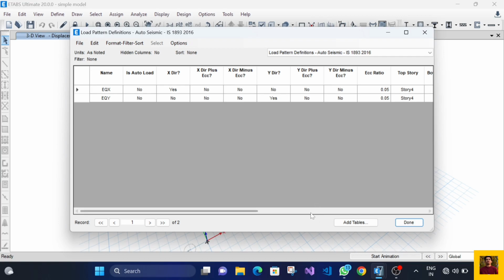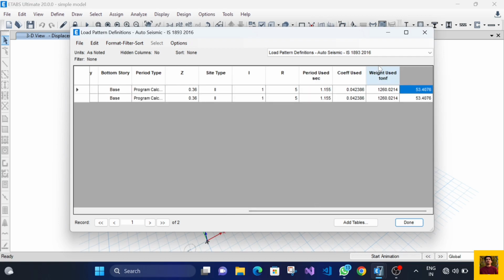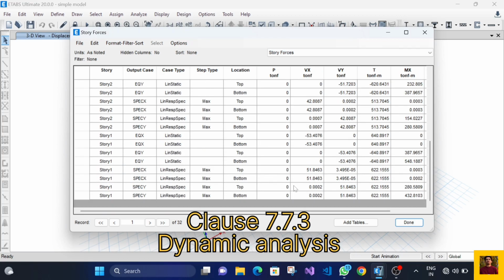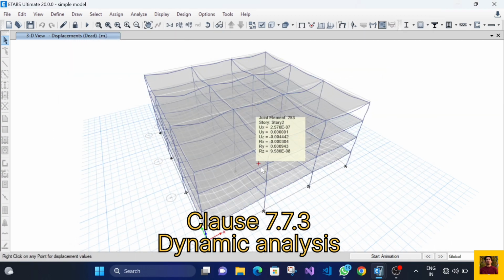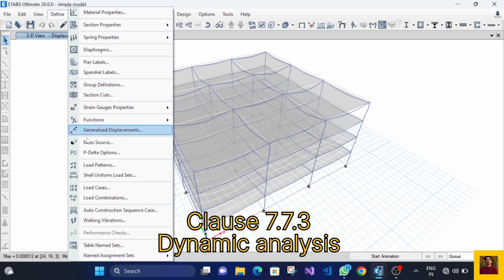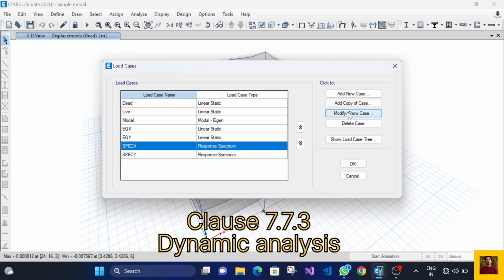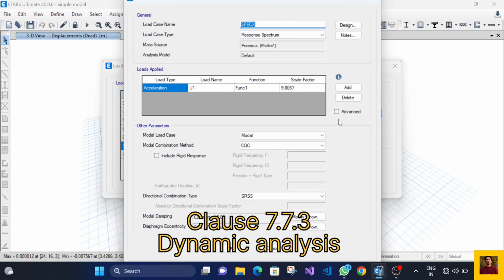Here you can see the base shear value and the response spectrum values are different. We have to match both base shears, as the code specifies for the maximum considered earthquake level. The spectrum must be converted to the specific set of units used throughout the model by applying the scale factor given as the value of gravity as acceleration in the current units of your model.